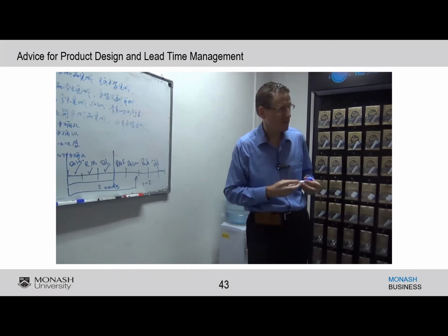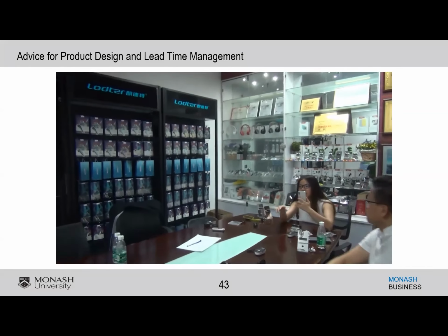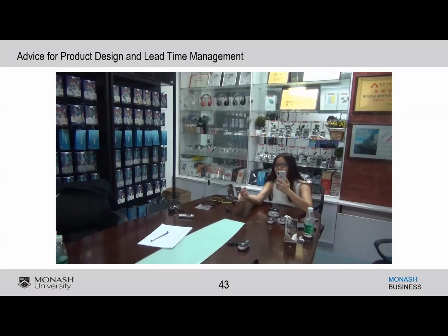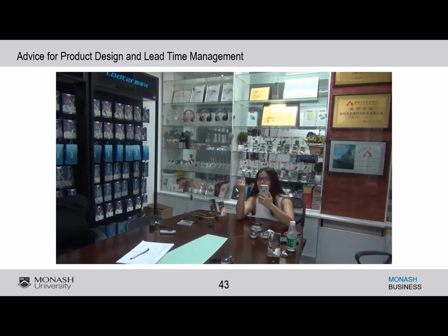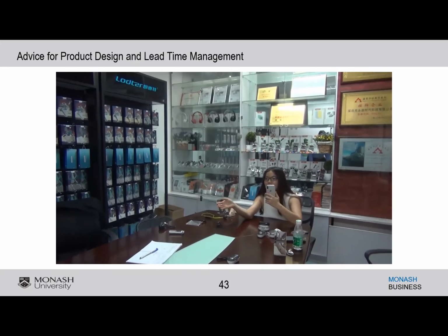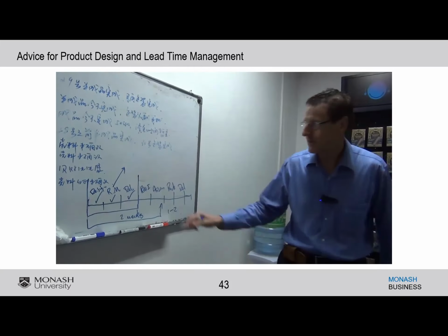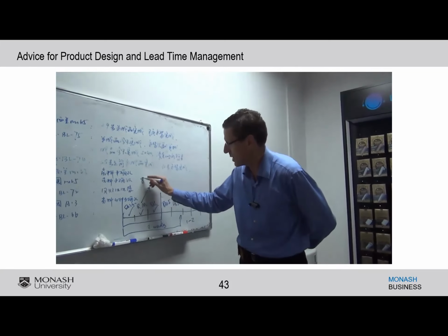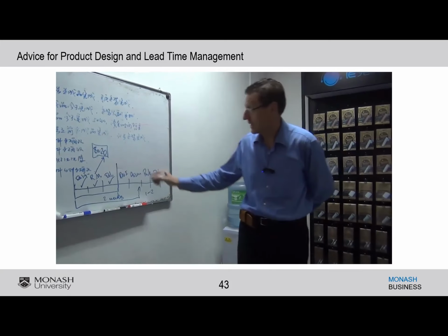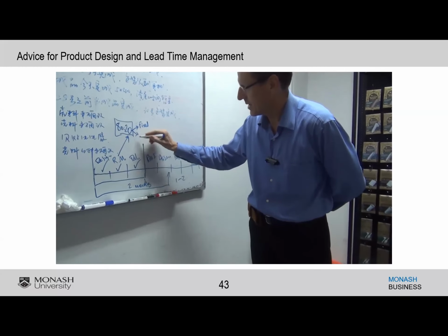Postponement. Okay. Postponement. That is, you are postponing variation in the product to the latest moment. What I was showing them was first of all, the product was earphones, and secondly, they had so many different types, and for the different types, they had different size batteries. When I was talking about that timeline, they had problems because some of the batteries weren't being supplied when they needed them because they had so many different types of batteries. So I said, why don't you try and do your design so you have the one battery for all of your designs. So then you can postpone. You're basically postponing variation in the manufacturing to the latest possible time.